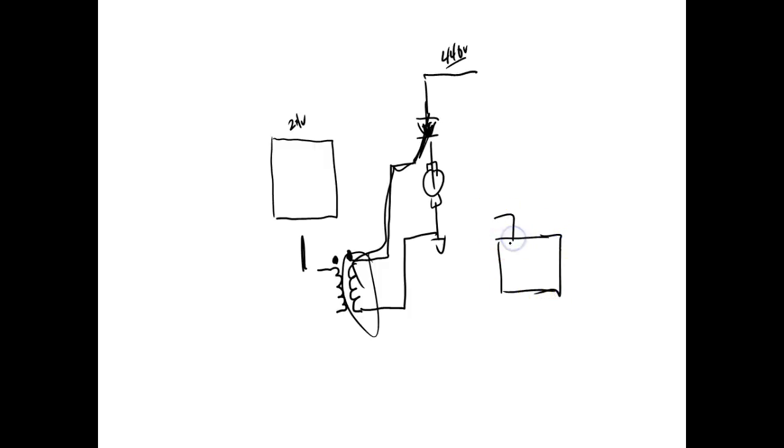So what they do is it's built in. It's usually got 6 pins, and then we'll have a photodiode, and then over here we either have a photo transistor, or right here would have an LED, and then we would fire the SCR on this side over here, and that way if something goes wrong, you don't screw up your computer.